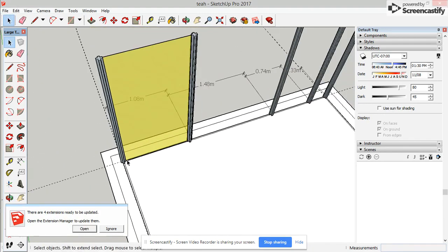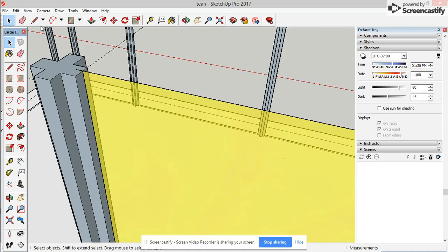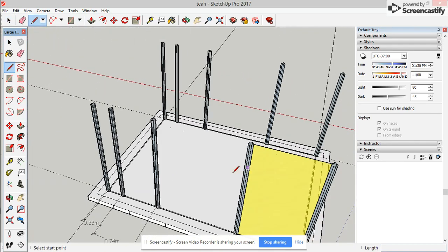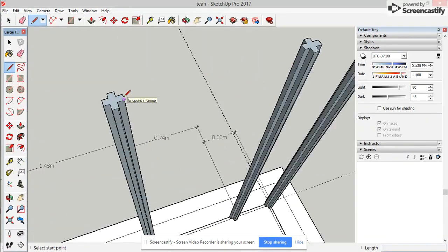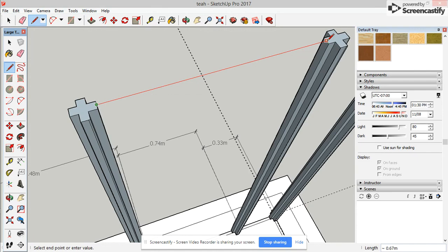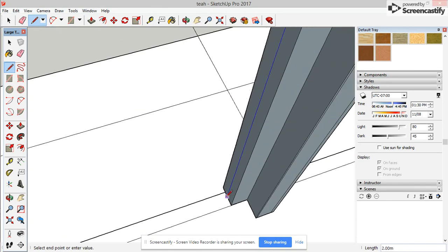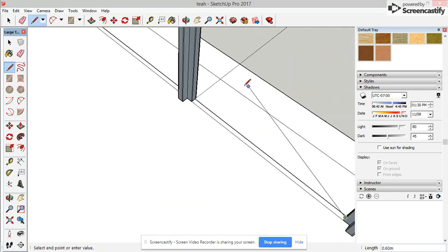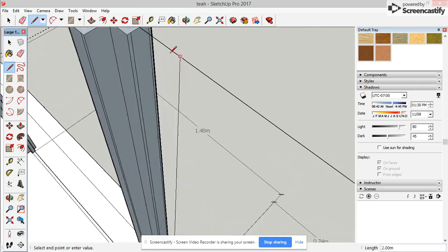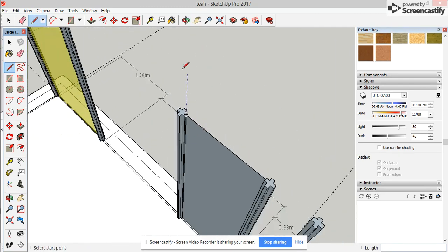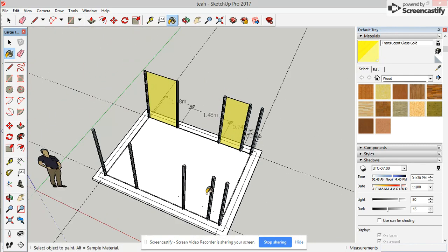You're going to start adding glass in between those panes. And what you can do is you can trace with a pencil tool from midpoint to midpoint. Now this is where the door is, because that's on top, but we can go from here to here. Go from midpoint to midpoint, all the way down, all the way around, up, and it should close it off and make a pane. There you go. I made it yellow. You do the same thing all the way around.